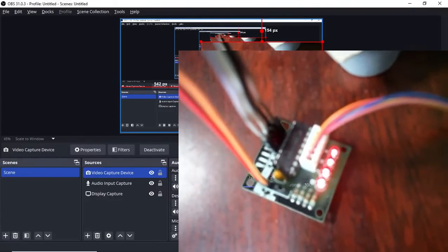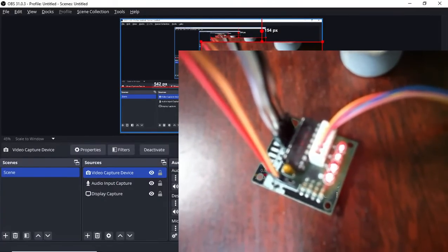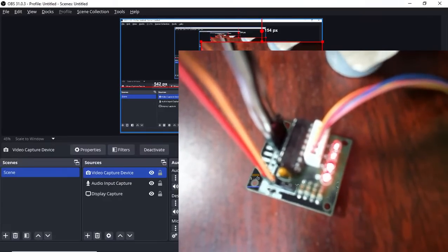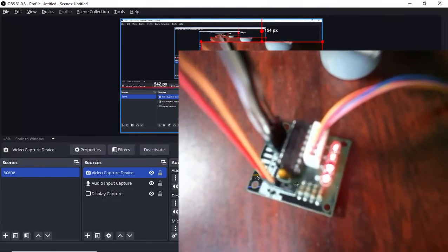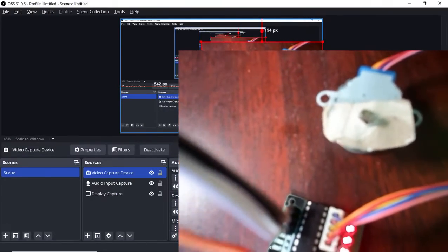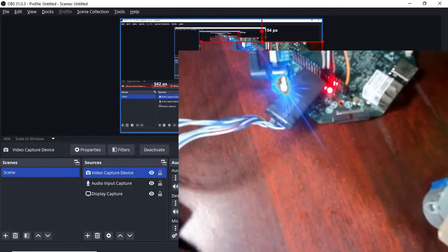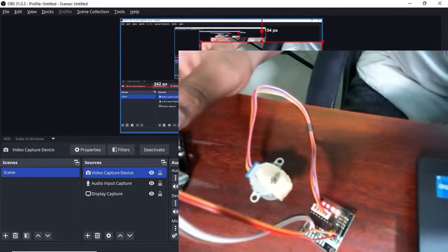If I increase the speed, meaning if I reduce the counter value, I can't see the rotation of the stepper motor, right? Because if I give a high frequency input to the stepper motor, it will stick. So this is the output for the stepper motor. It is rotating. So this is the FPGA. I just connected my FPGA and the stepper motor driver using jumper cables.